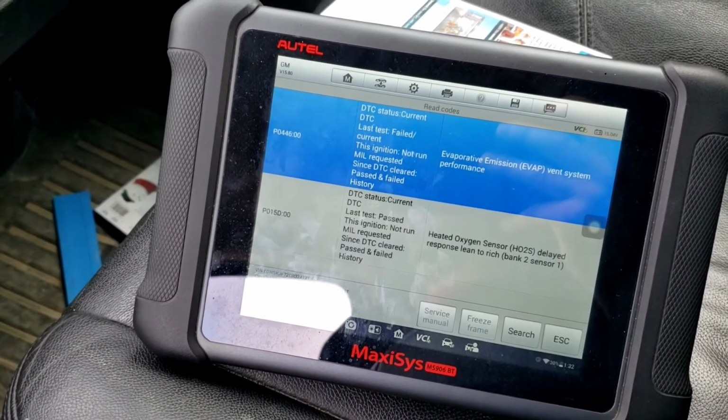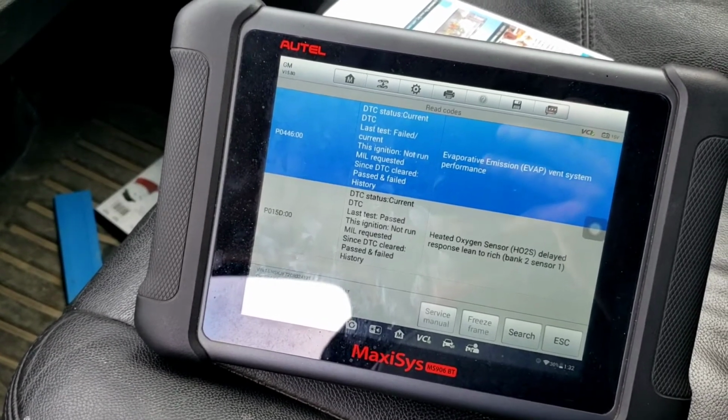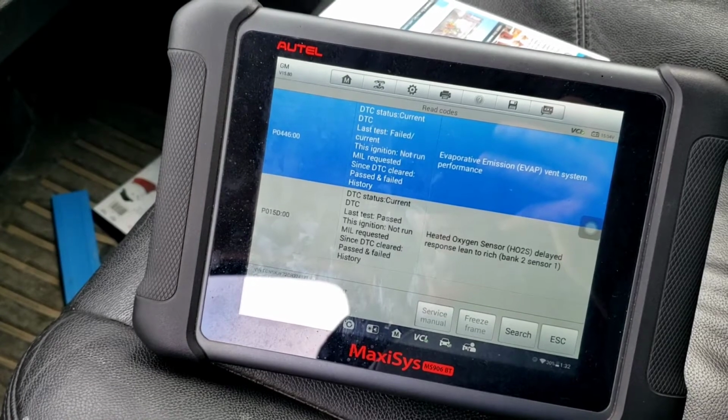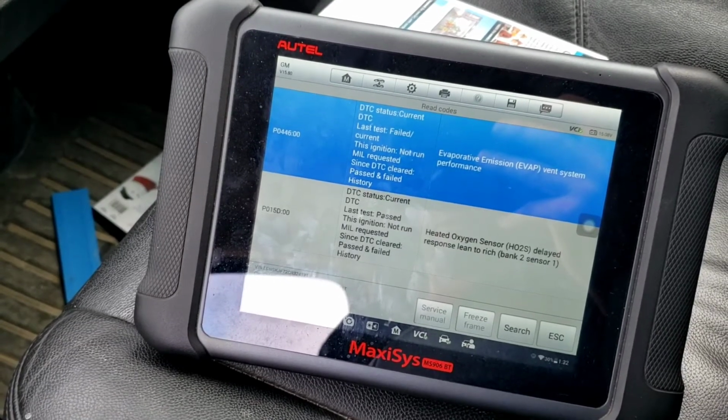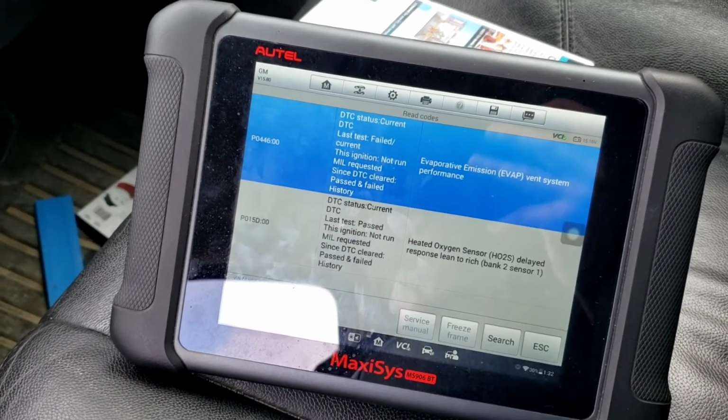So we just got to go through that, clean it, redo the same exact test, and then you can force it to do its test. You don't have to wait for the light to come back, and you can take the scan tool and force it to do its drivability test and go from there.